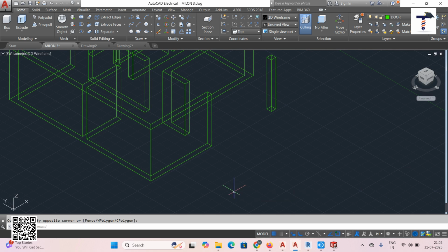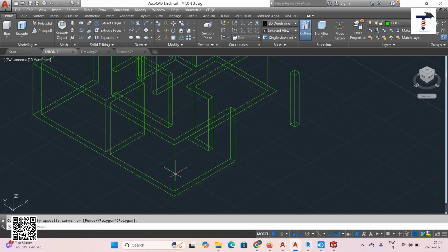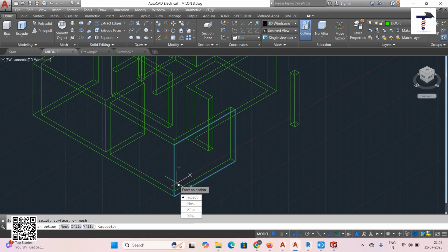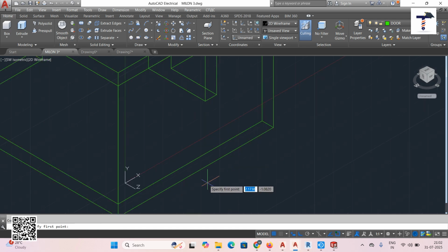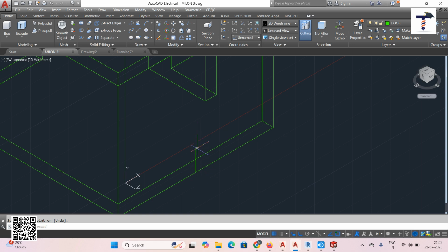So now after that here we can create, suppose, face UCS. So now this one is face UCS, this is the surface, and then enter. Okay, so now that is the XY plane here. After that we can create one line, that is called sill height, from the basic, means from the floor. Okay, so after that we can create here one rectangle as per your dimension.